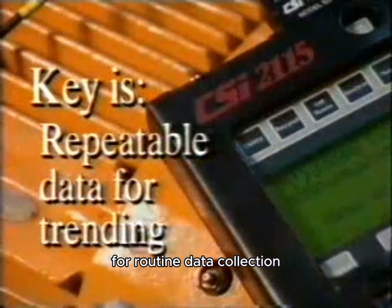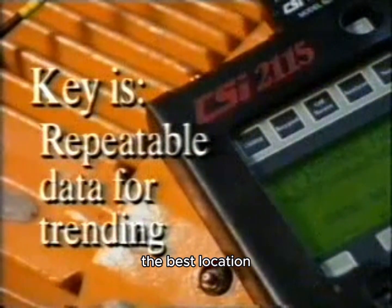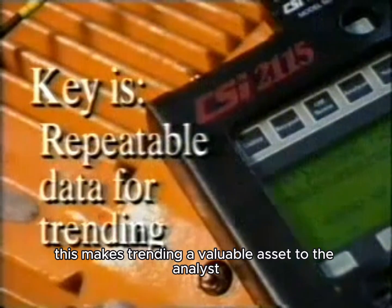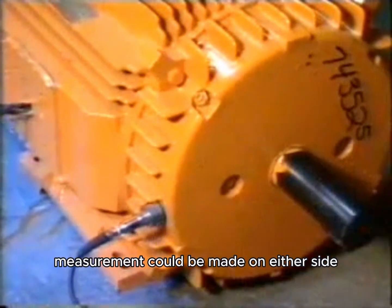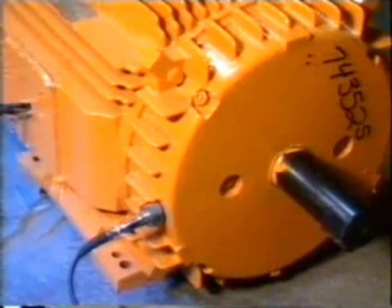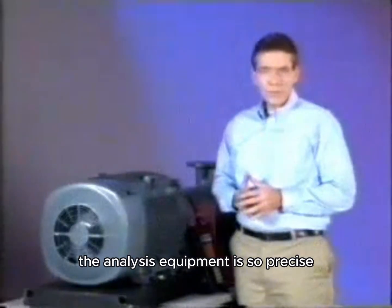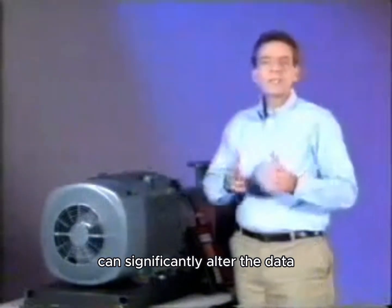For routine data collection, remember that we may not be able to take the time to get the best location, but that the data should be repeatable. This makes trending a valuable asset to the analyst. Although the horizontal measurement could be made on either side and provide good information, it is best to maintain the same horizontal measurement orientation from one routine survey to the next.